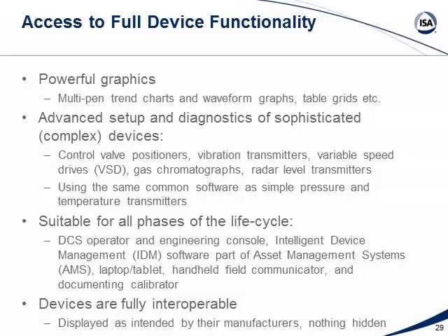They said, EDDL is the core part of doing this device integration. But when the device requires something advanced, you can build more of an app, I'm going to say. Not so much a full monolithic application, but a small little app to do that specific function. And the nice thing about FDI is that it pops up seamlessly with your EDD-based menu. So from an end-user perspective, you don't really notice any difference at all. But the power comes in with that separation between a more generic text-based approach of EDDL and the Windows-based approach.